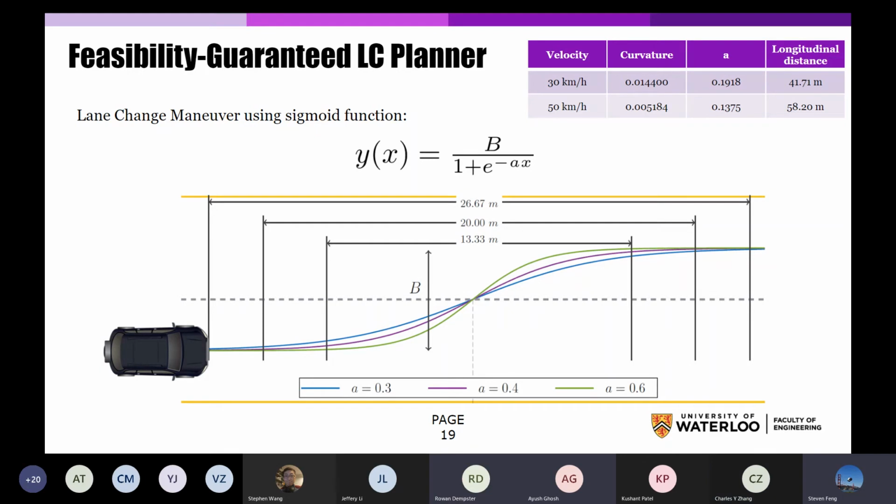Yeah, and the nice thing about the MPC approach, as well as the title of this presentation, is simultaneous local planning and control. The outputs of your planner are just direct control actions, whereas the output of the Frenet planner is a path, but then you need to implement another control layer underneath that path to actuate it.